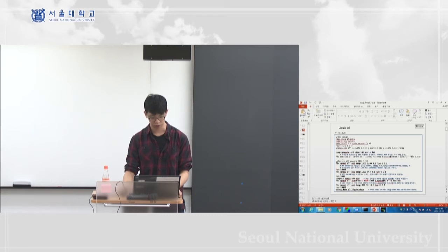So with this NPT ensemble, we're gonna run the simulation for 10 picoseconds, and then we change the temperature to 943 Kelvin, which is 10 Kelvin more than the melting point, which is still liquid, but we're gonna make it a more realistic temperature, this 900 Kelvin. And the rest is the same. The only exception is this temperature term. And we're gonna run it for 5 picoseconds.